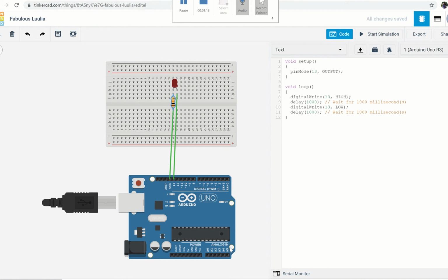And so a quick overview about the Uno. Over right here, it's our analog. There are a few analog pins that start with A, and then you also have two different voltages, 3.3 and 5 volts, a couple of grounds, and VIN, which means the input voltage you give. Then over on this side, it's all digital pins, from 0 to 13.